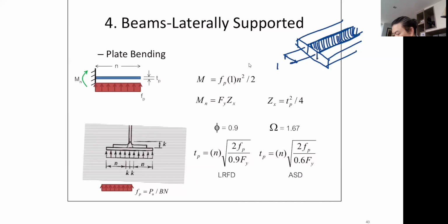Okay, and when it becomes 1, it means that your bending moment is simply this, right? Stress, which comes from the load divided by the area of the plate, multiplied by L square over 2. Basically, it's WL square over 2. It's either this, or if you're more comfortable turning things upside down, you now have this model.